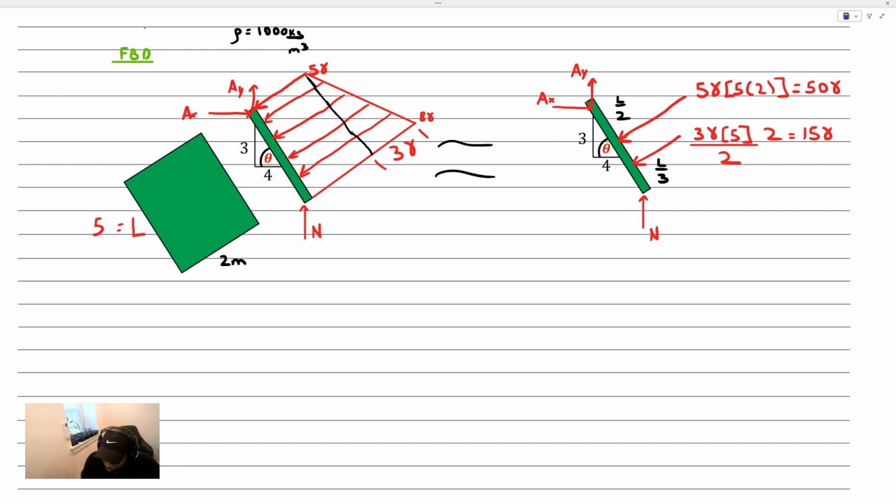If we're looking for that normal force, which is exactly what we're looking for in the problem, we can sum the moments about point A and make sure that we get a 0 value. What that means to me is that once we go at point A, those two forces won't produce a moment. They have a 0 valued moment arm. And we'd have the two contributions that are clockwise.